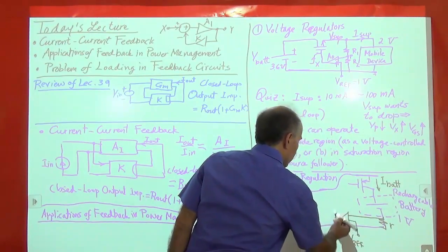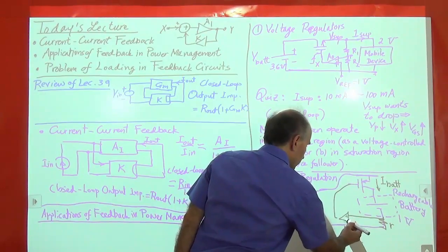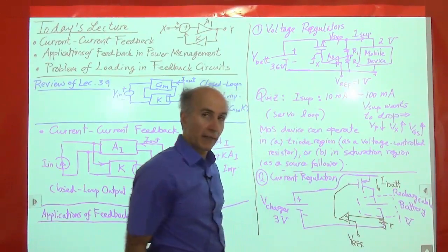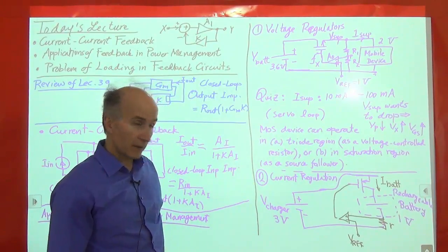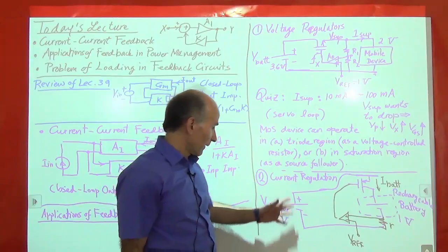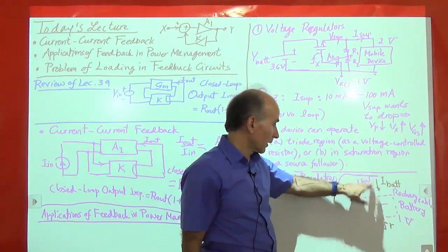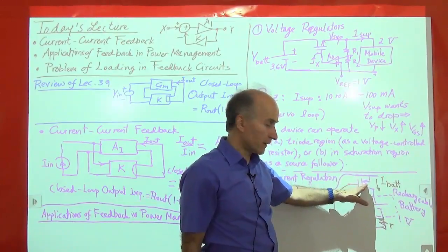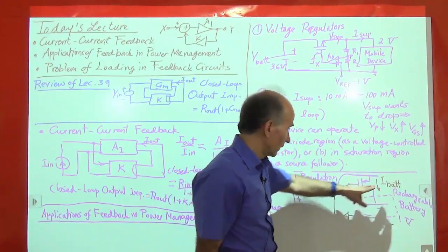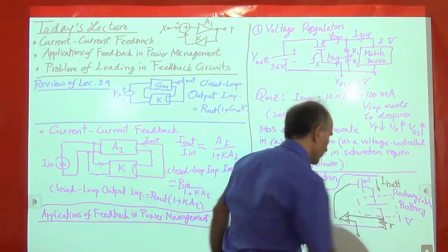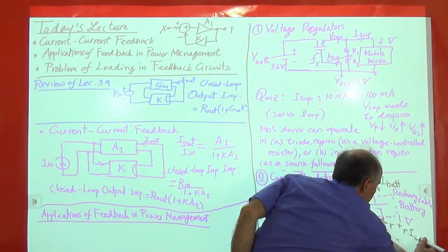And then the result goes and controls this current source. In this case, this should be positive, this should be negative, because we would like to have negative feedback. So how does this operate? You can see that we have a charger here. The charger is 3 volts or something, it doesn't matter. This is the supply of this current source. This current source says, I need to deliver a certain current. How is that current defined? Well, I battery flows through R, so this voltage is R times I battery, right?